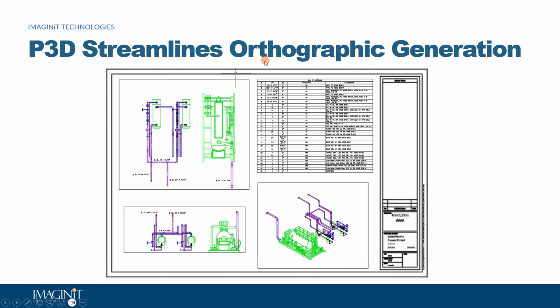This bill of materials has an ID number, and there are features where you just right-click your mouse, and you can annotate the drawing. In this case, we just added some center elevations. You can also add the ID bubble to point to the different components of your Plant 3D model, and you can add dimensions as well. So it's very straightforward how to create this drawing, and quick.